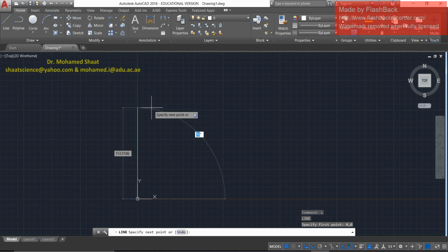How can we switch between the length and the angle? You can simply press the tab key. Use the keyboard and press the tab. You automatically gonna switch between the length and the angle. So for example, you can specify a length, whatever it is, like 200. Then you can switch to the angle, just tab to the angle. As you can see, it has a constraint over it, locked here, the lock icon. It means that right now it has 200 millimeter length. Then you can specify the angle, let's say like 45 degrees, and press enter.